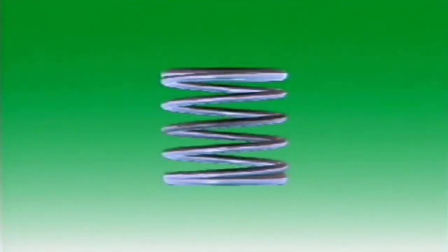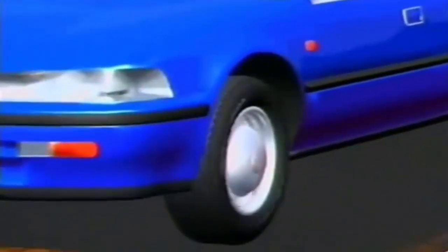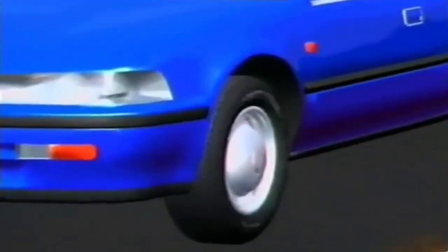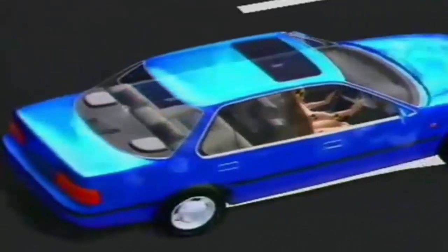When a vehicle strikes an uneven surface, the springs are deformed from their original shape. They return to their original position, but tend to overshoot and set up oscillations. This makes the vehicle bounce up and down, which makes the ride uncomfortable. It can produce forces that make the tires bounce, and a bouncing tire won't grip the road surface well. Shock absorbers have a marked effect on how well tires follow a road surface. They damp the natural bounce over the road and reduce spring oscillations.